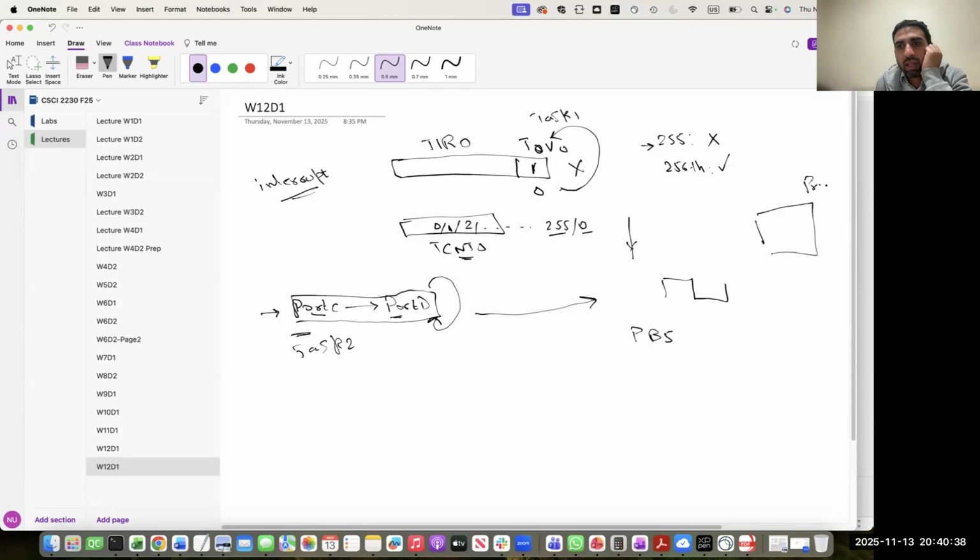The microcontroller, let's say it was in the middle of here, will stop and start executing this program, which will take responsibility of generating this square waveform on the output PB5 every time this flag is set equal to 1. And then it can come back and start executing exactly at the same point where it was before, at the time point when the flag was set.